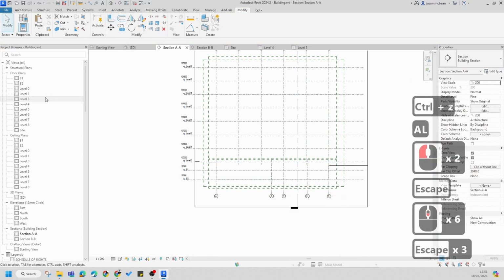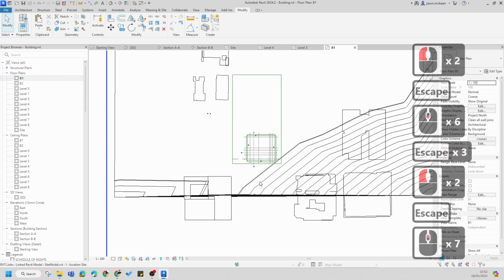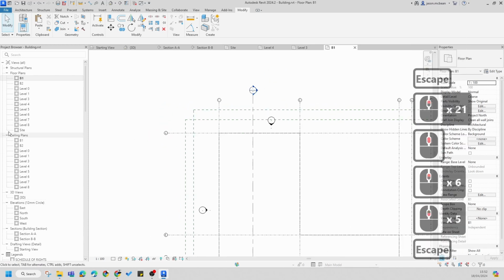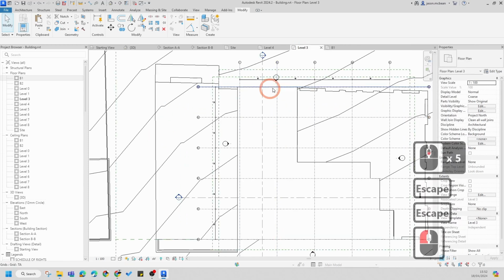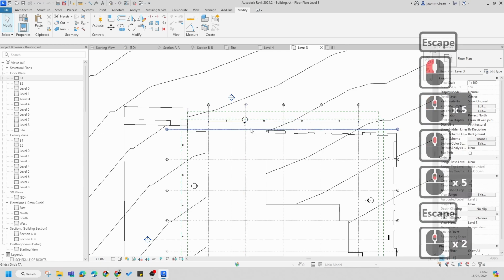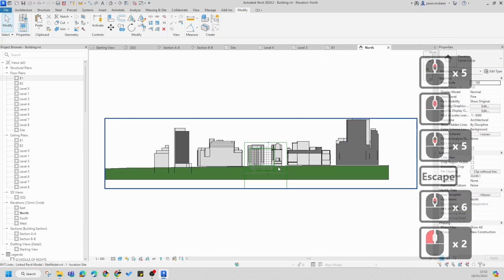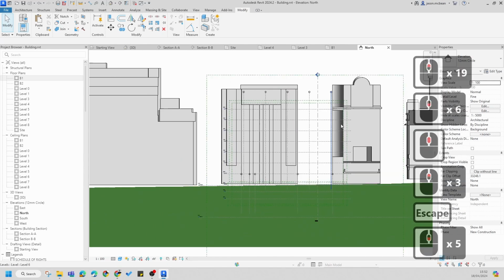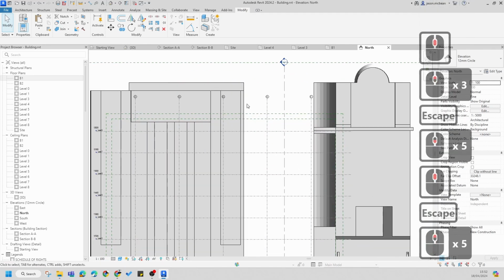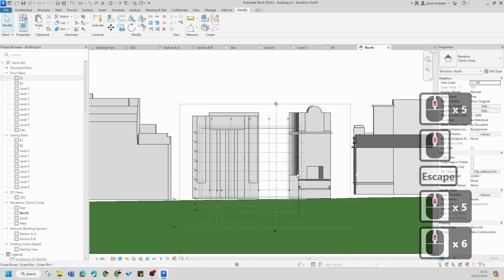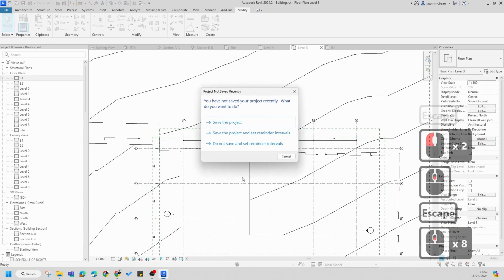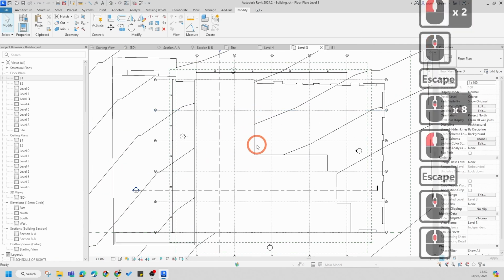Okay, now if I go to my basement view, you'll notice I'm going to have one grid system available. You'll see that I have my first grid system available. Now if I go to my third floor now, I'll have a different grid system. So that's how you're going to manage a series of different grid systems. Okay, your elevations will work the same, but remember the grid system below ground you probably won't see. Remember our building's here in the middle. So you can see that the grid systems work, and that's what's nice about scope boxes. So that's the first part of the exercise: getting your grid systems established, using your scope boxes correctly.